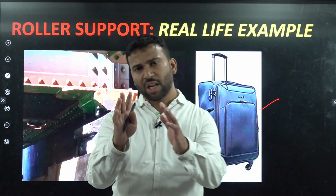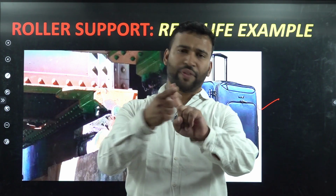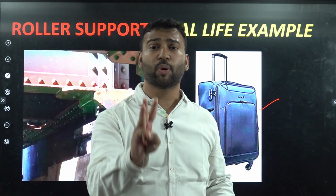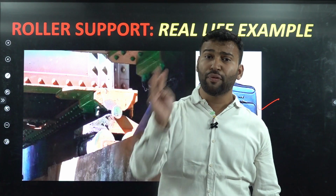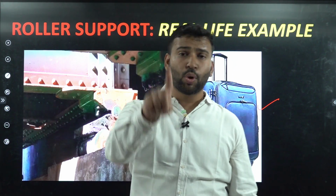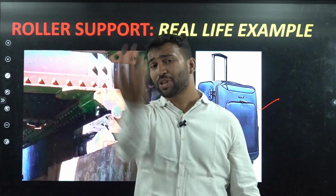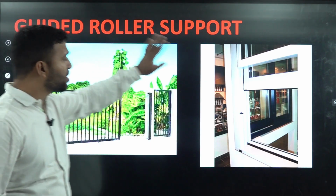Okay, so till now we have covered our basic supports, that is the roller support, fixed support and hinge support. If we are talking about the fixed support, we have three external support reactions, that is horizontal reaction, vertical reaction and moment. In case of hinge support, we will have only two reactions, that is vertical reaction and horizontal reaction. In case of roller support, we will have only one reaction, that is in the vertical direction. That's it. Now we will move towards some special cases of support, starting from the guided roller support.